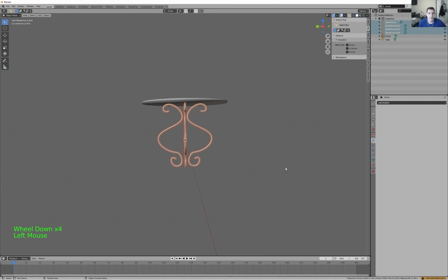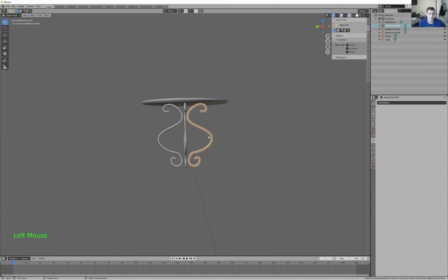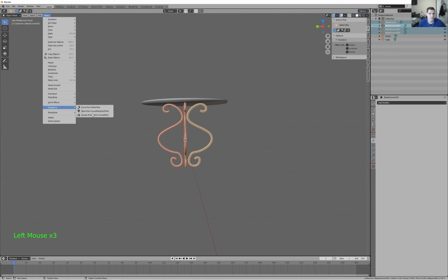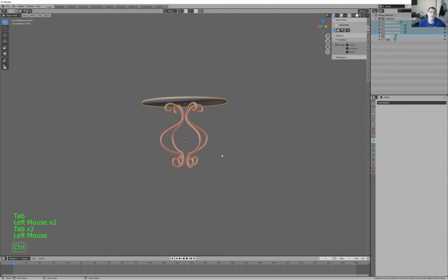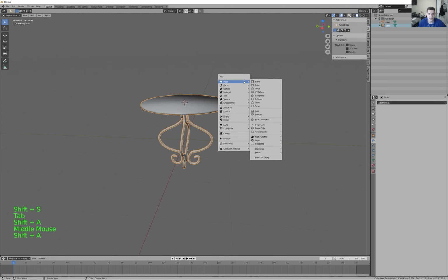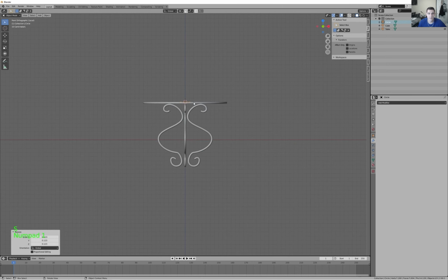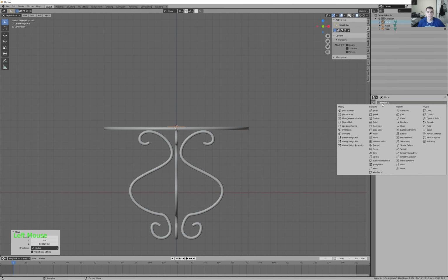So the way we do that is we select the curves. Make sure you have one selected as a primary, so that yellow one, and we're going to go to Object, Convert, Mesh. You can also press F3 and do it that way. And we're going to do Control J on all those meshes, and it'll combine them all together. And you can see we have a bunch of vertices and things like that. The next thing is we're going to add in a vase.